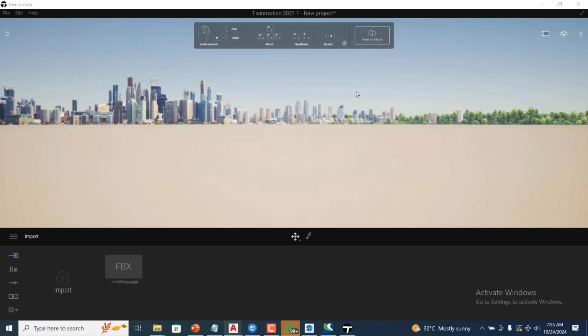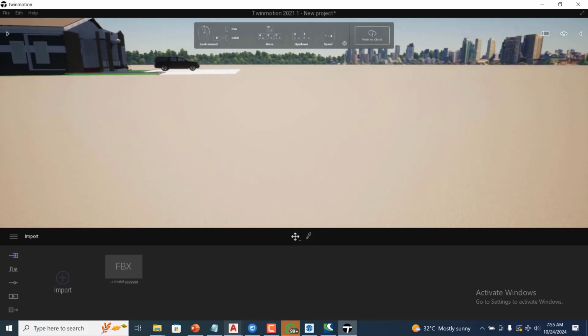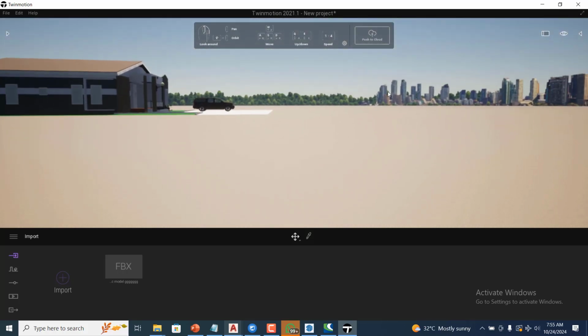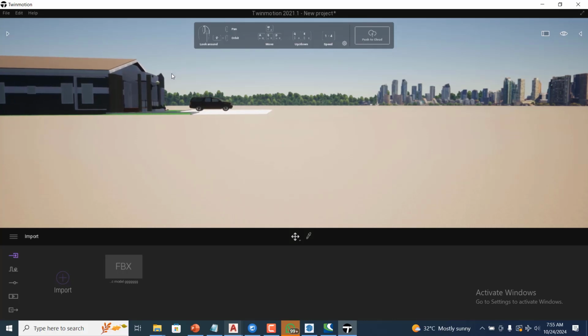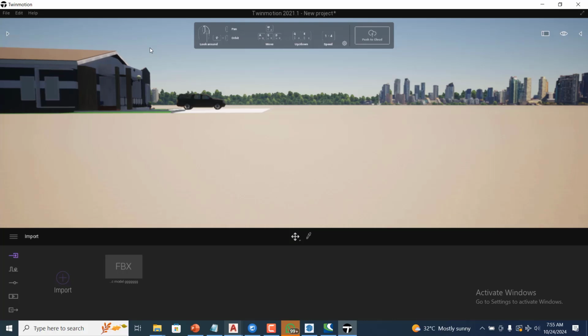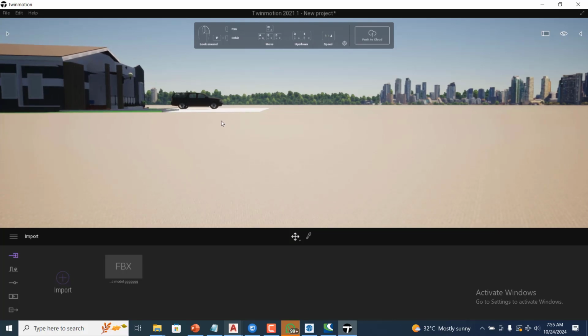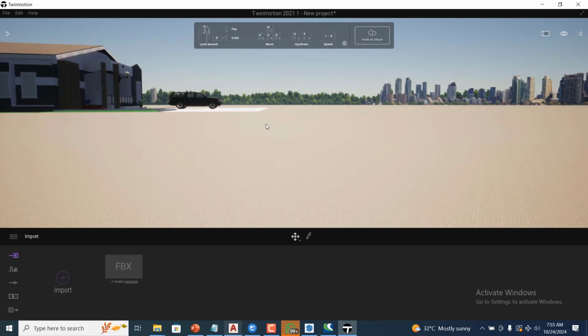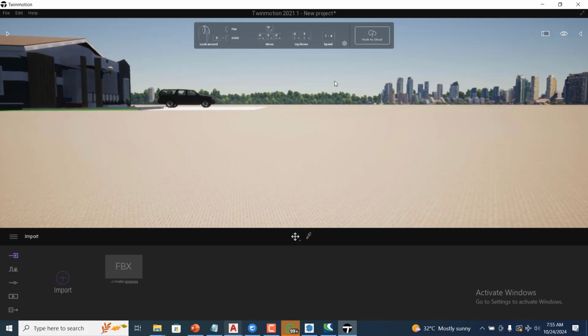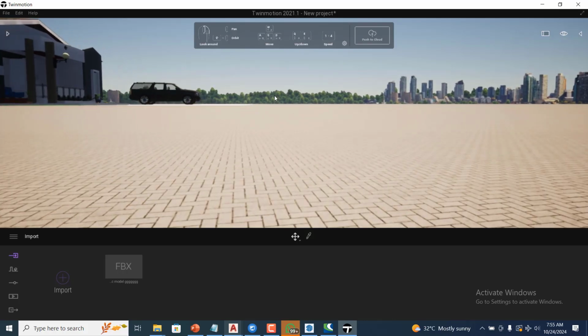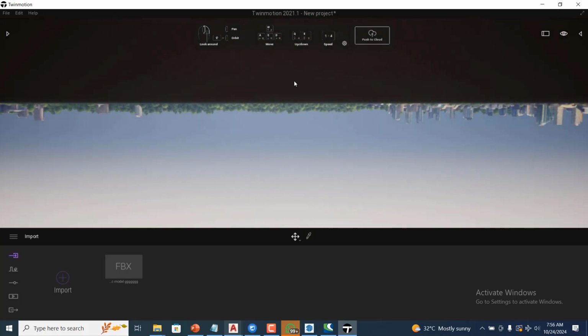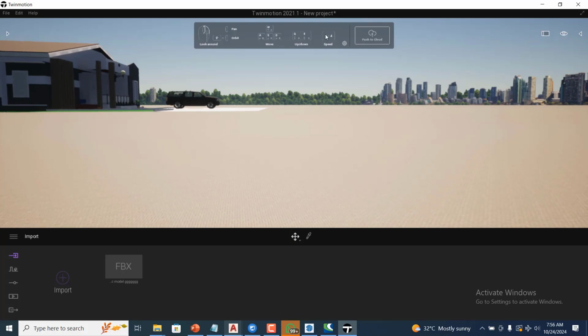If you hold on shift and you press and hold your right click of your mouse, you can easily hover and just orbit, right? So if you want to zoom this faster, you can hold on shift, it goes faster. You can see the numbers there determines the speed. If I press number 2, you can see the speed will increase. If I press 3, the speed has increased more. If I press 4, the speed is even more. Okay, so this is 1 from 1 to 4.